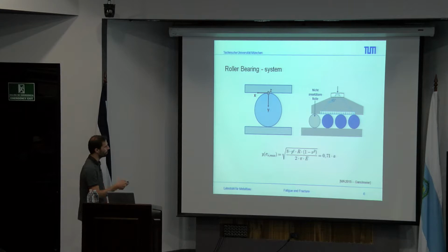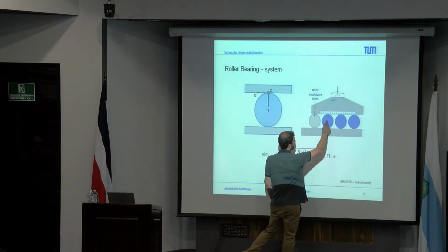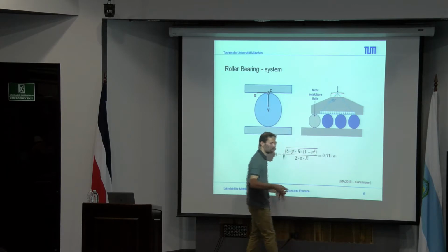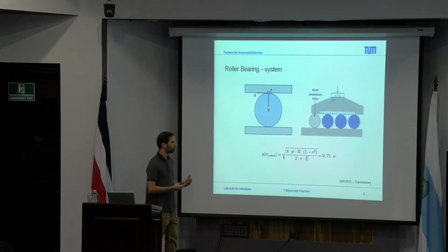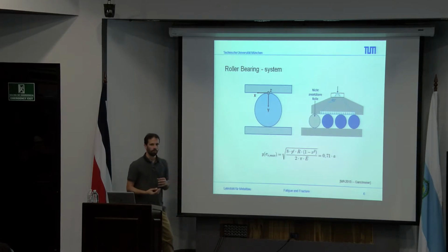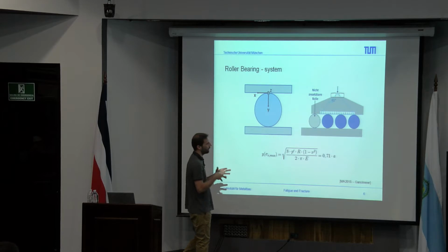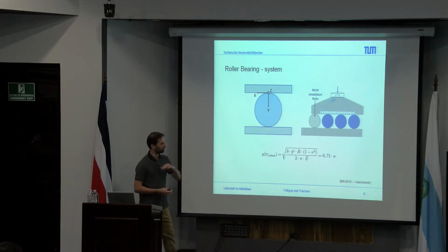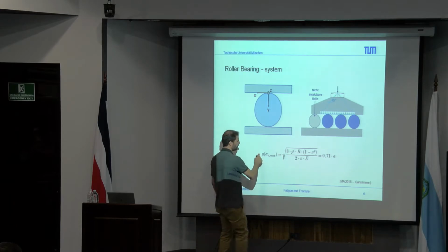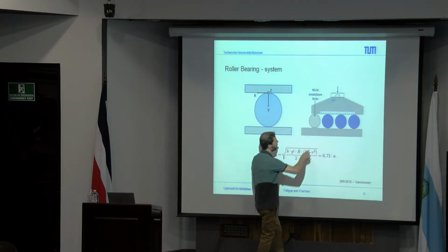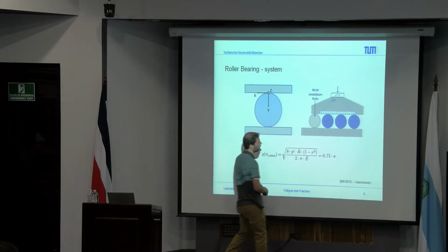So we have here some contact information, and due to the loading at this point we have the highest pressure, which are also going above, theoretically above the yielding point, but due to the three-dimensional state, usually you're always under the yielding point, and you can describe here the information in the y direction by this quite easy formula.